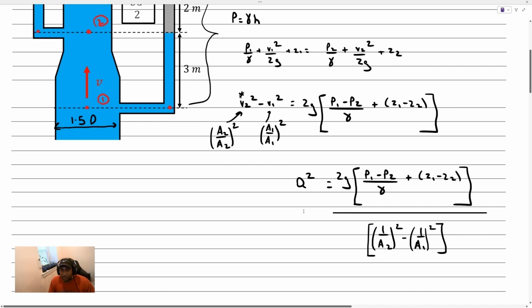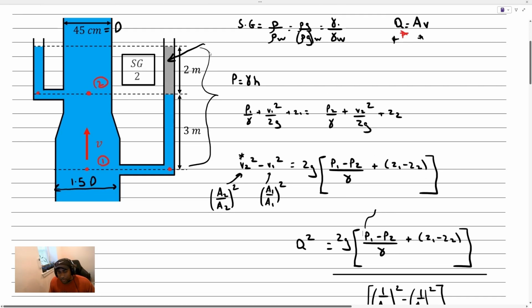We mentioned the manometers and how they could be used to find the pressure. What I know is that the pressure at 1 is given by rho g h, where I have 2 different fluids here. If I start at this upper surface, which has a gauge pressure of 0, I descend inside the fluid until I reach this second point where the fluid is going to change.